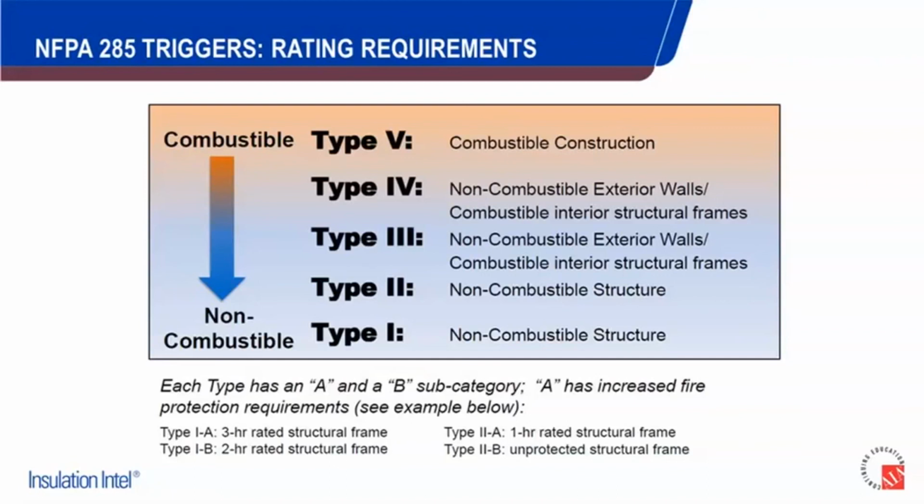The Type 1 through 4 structures, though, as you see listed out here, call for at a bare minimum non-combustible exterior walls, or a fully non-combustible structure if we're getting into tighter, more stringent requirements: high-rise structures, large assembly halls, things like that, which dictate a fully non-combustible structure.